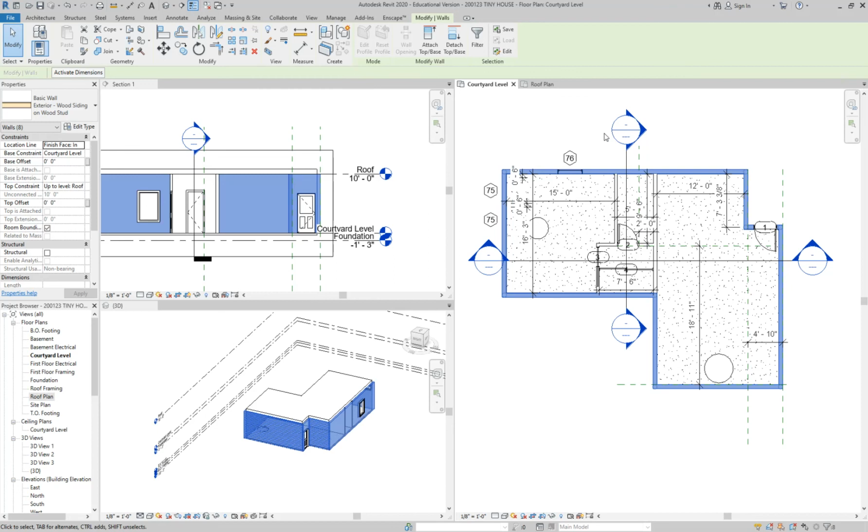It didn't select that wall, because my walls extend. But we don't freak out. What do we click to grab an extra wall? Control. To add another wall, hold Control. If it grabs something you didn't want, hold Shift to get rid of it.